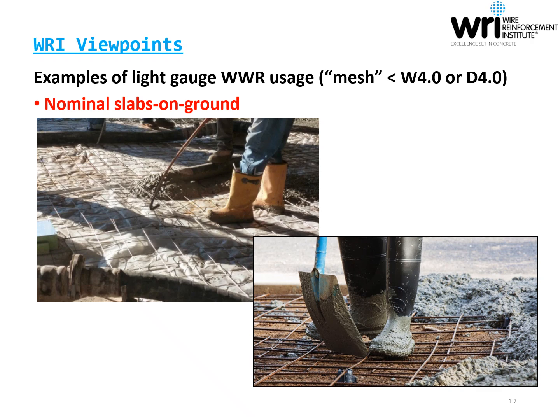For a slab on ground, depending on the design criticality, the specifier's tolerance may be perceived to be stringent or comparatively lenient, and this in turn can affect whether the light gauge welded wire reinforcement solution requires supports at 8 inches on center or 12 inches on center or even 36 inches on center. The point remains that for a given set of design and tolerance inputs, a construction solution does exist, though it may very well diverge from a contractor's preferred mode of economical operation.